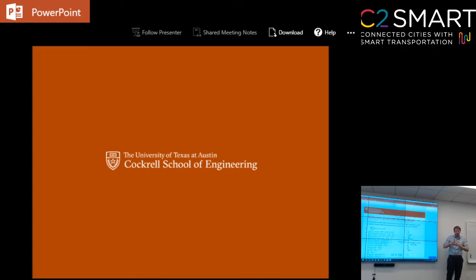So you have model parameters that are, for example, the type of fundamental diagram that you use, the free flow speed, congestion speed, capacity. All these are parameters. They can be different for every single link. You also have junction coefficient parameters, so splitting ratios. But all these again are parameters of the model, so they are not states, and they are not inputs, so we don't modify these at all.